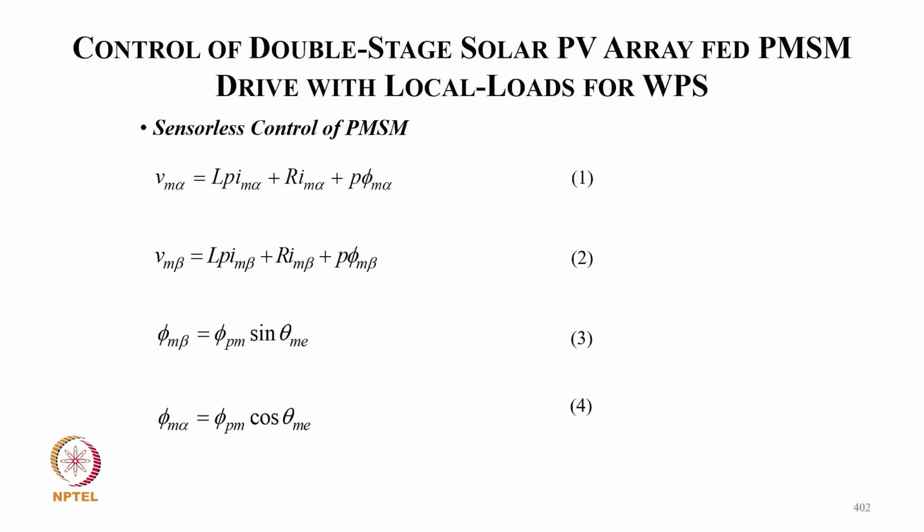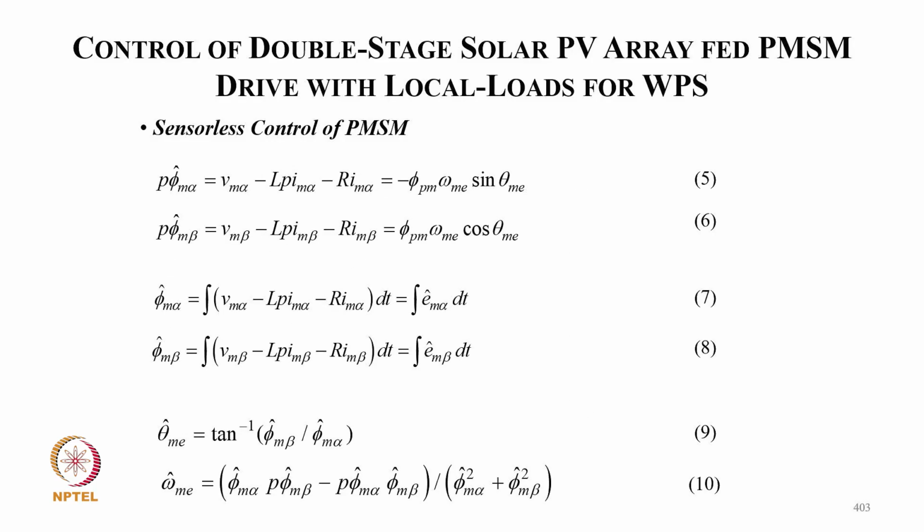So coming to sensorless control, V_mα equal to L p i_mα plus R i_mα, and p ψ_mα, and V_mβ equal to L p i_mβ plus R i_mβ plus p ψ_mβ, and ψ_mβ equal to ψ_PM sin θ_me, and ψ_mα equal to ψ_PM cos θ_me.